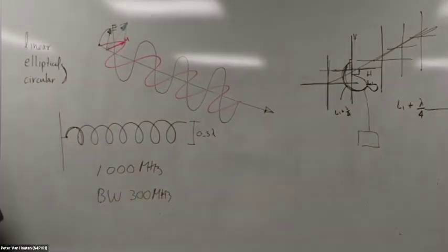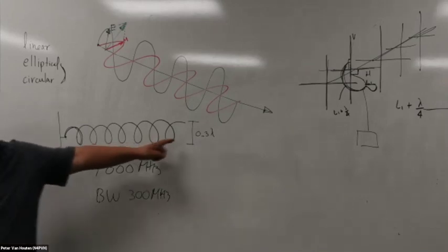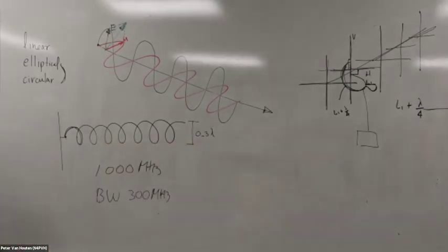That's a lot. These antennas are normally used at high frequencies. Why? Well, 0.3 lambda. If we're going to use it on 2 meters, that helix will be over 2 feet in diameter, and long, maybe from here to the wall, depending on the number of turns.